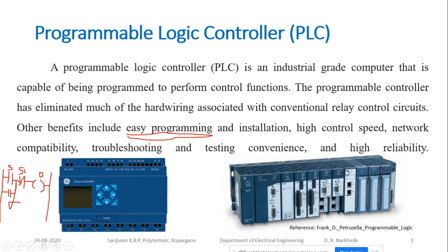And this is the PLC which is used in the industry, that is a modular PLC. Both PLCs are used in the industry, but this is used for small applications, this is used for larger applications. Now it has your power supply module, then your PLC module, then your communication module, then input module, then output module, again input module, output module. A number of input modules and output modules can be stuck together, so this is called modular.